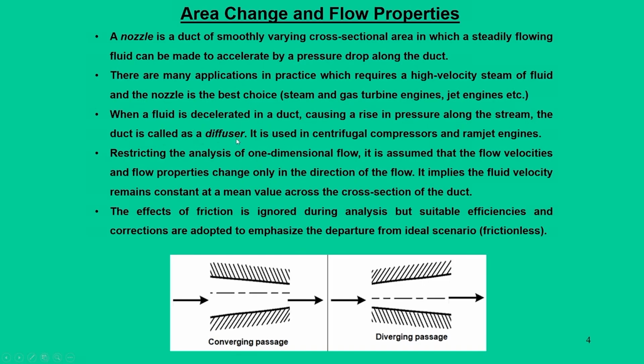So, that is called a diffuser, and typical applications include the passages of centrifugal compressors and ramjet engines, where the intake systems are designed so that the flow has to decelerate, causing a rise in the pressure.